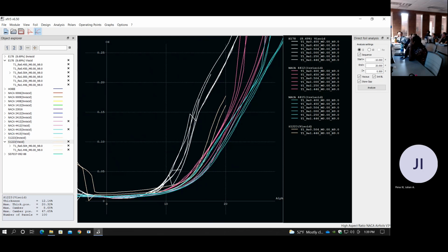So I was mostly looking at your 2D airfoil CD and CL values. You have to take flight mechanics to find out, but this is the starting point. This is the drag formula, and then you can determine the gliding range, endurance, and other things based on this data. If you do a good job in this aerodynamic analysis, this is going to determine your performance.